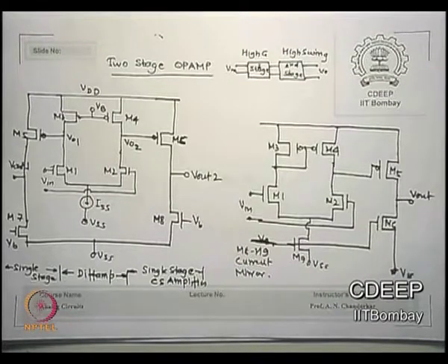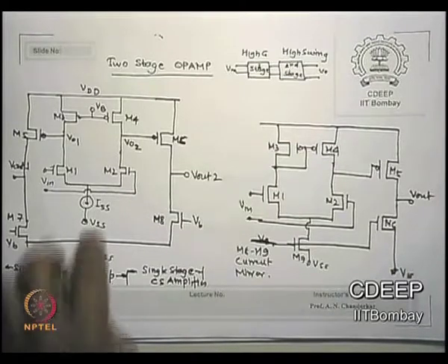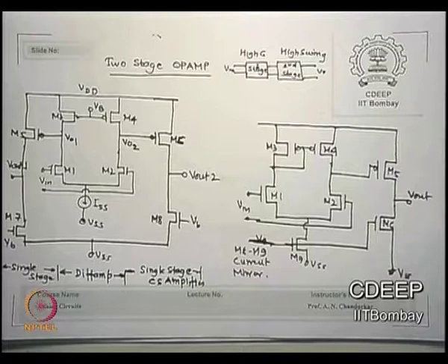The typical number of transistors required to create an OPAMP is typically 22 and may extend a bit here and there up to 30. So it is not a small one-transistor circuit, it has a large number of transistors. Even for the 2-stage OPAMP, the transistors related to ISS have not been shown, which may be more than 2, that is 3, one coming from mirrors for example. So you keep adding such transistors, you will find as many as 30 transistors or at least 22 transistors are required to create an operational amplifier.